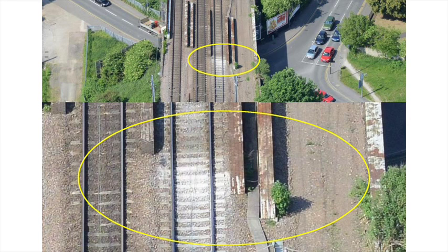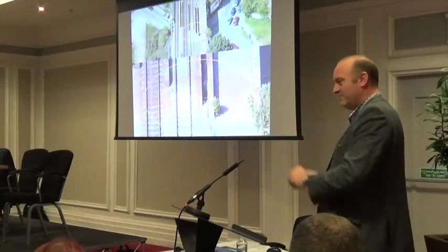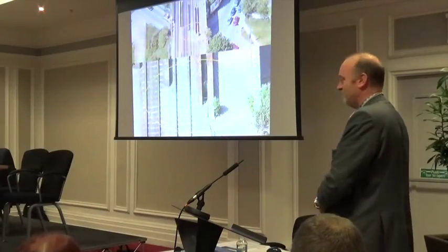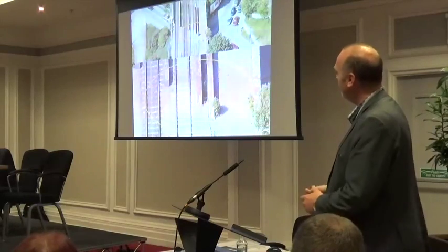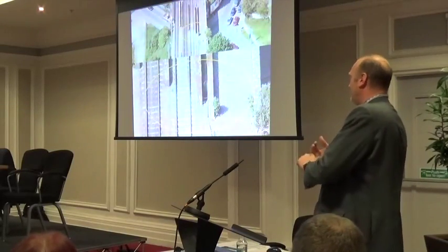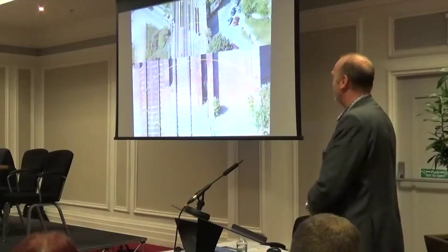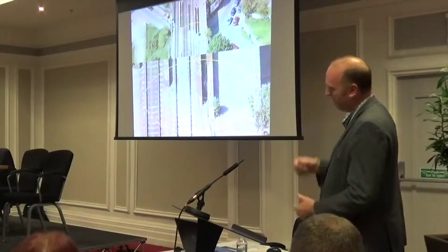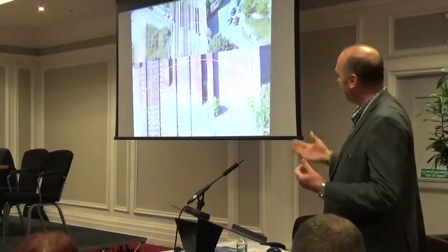As always, I have a focus on broken rails and rail defects, so I've been picking out where our rails broke. I get lots of good pictures now from the engineers locally: close-ups of the fracture face, pictures of the sleeper, with comments back saying ballast condition typical, pad condition okay. You go back and look at the aerial photography, and it's about having more data.